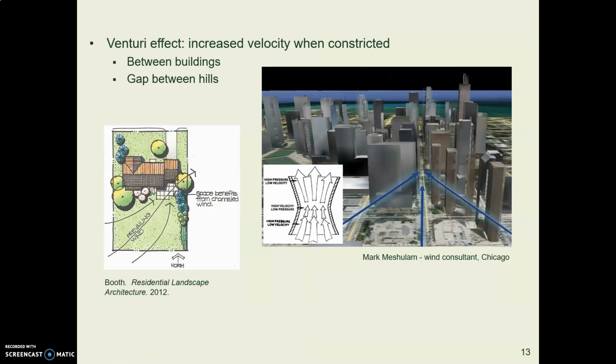You've probably heard about this urban canyon effect, especially in the city of Chicago, where there are tall, solid buildings close together, and the wind comes blowing through there, and just like gasoline in an old-time carburetor, there's a Venturi effect. So when the space that the air flows through necks down, the velocity increases, and you get this high-speed